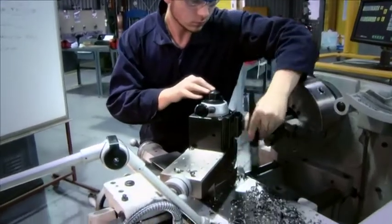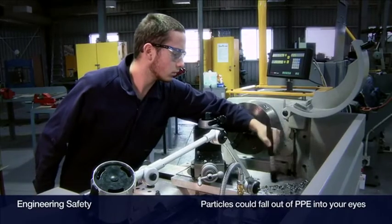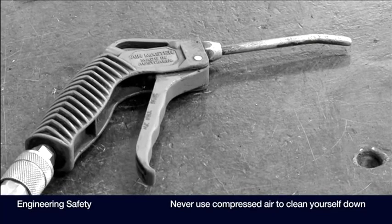When you clean up after a job, you need to take extra care removing your PPE, as particles could fall out, possibly into your eyes. Never use compressed air to clean yourself down under any circumstances.